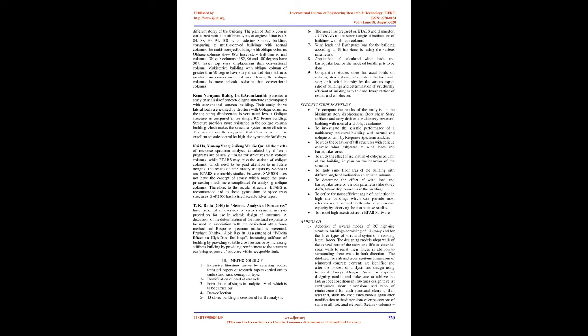First, they are subject to static and dynamic loads. Second, the building distributes wind into and around itself. It is called wind pressure. The wind pressures on the building are influenced by building geometry, angle of wind incidence, surroundings, and patterns of wind flow. There are many situations where databases, codes and standards, and analysis methods are available but cannot be used to measure wind pressure coefficients and wind loads on the claddings and support systems of structures. For example, when the aerodynamic formation of the structure is unusual.